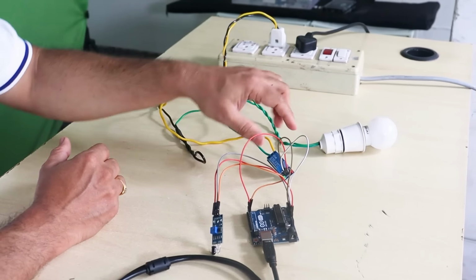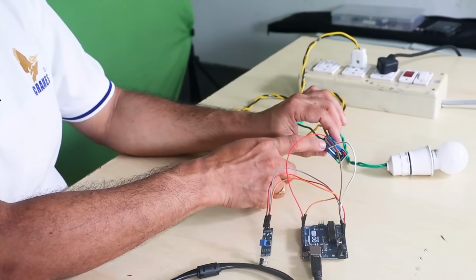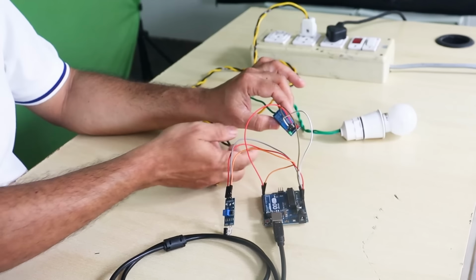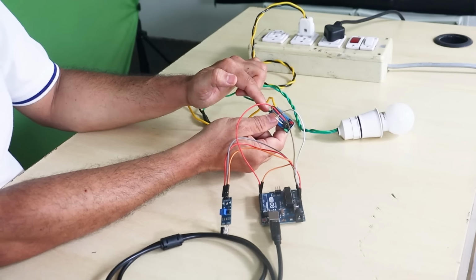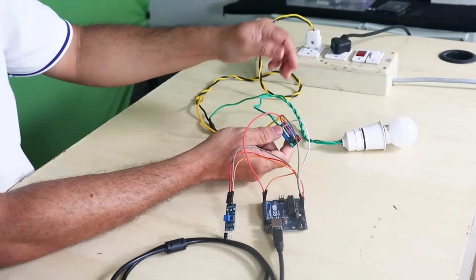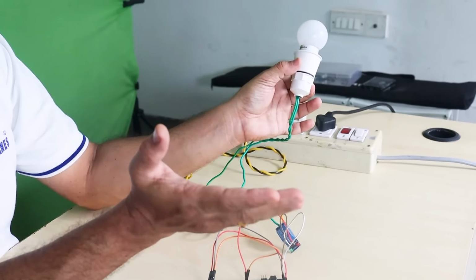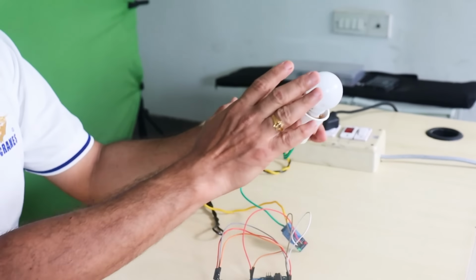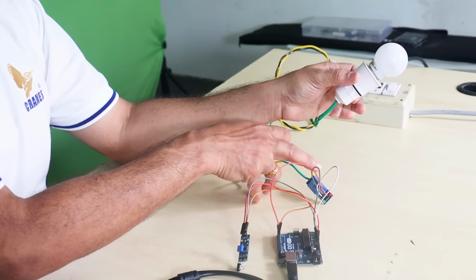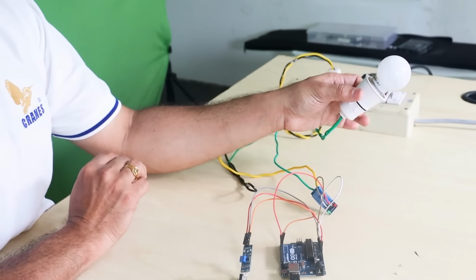Suppose I want to turn off, then I will send a low signal to VIN, and that is how the magnet inside this relay gets de-energized and demagnetized. Then our state, which was common, will come back to normally open on the relay side. When the relay comes back to normally open, the circuitry of the bulb will be broken open. So your bulb will not glow. If you want it to glow again, you have to give a signal to the relay, and once the circuitry is closed, your bulb will glow once again.